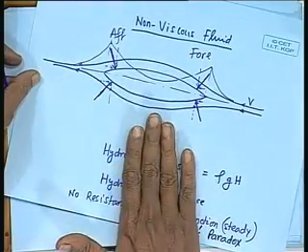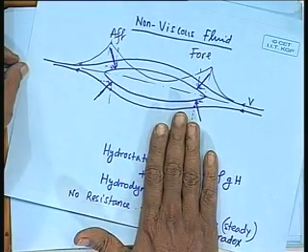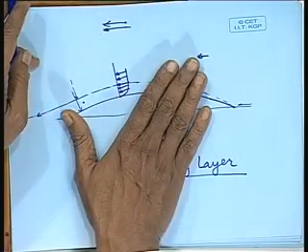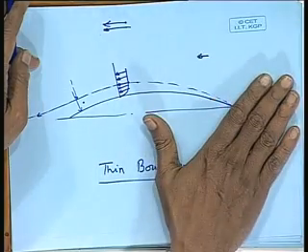We saw previously that the pressure resistance here was 0, resistance due to pressure. Here we are saying that it is no more 0 in a viscous fluid, but a little bit of pressure resistance now starts acting because of the development of the boundary layer. Is that clear? So, this is called viscous pressure resistance. Okay. So, we are still on the submerged body.